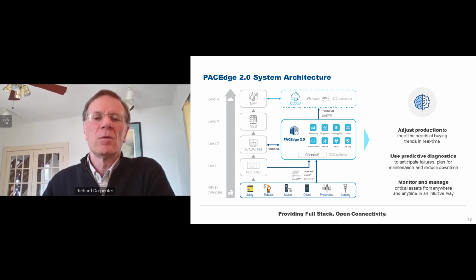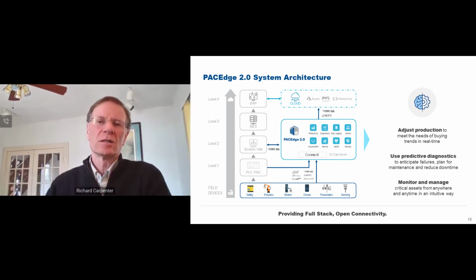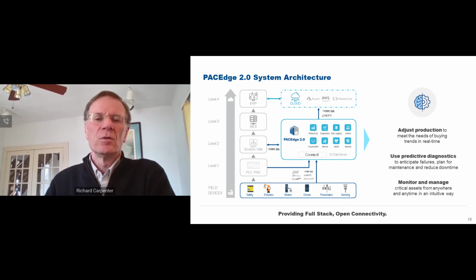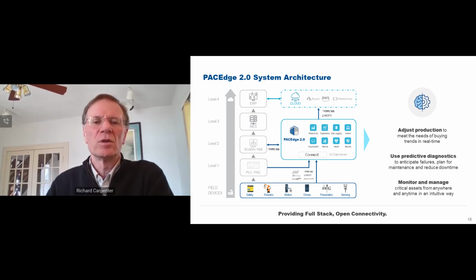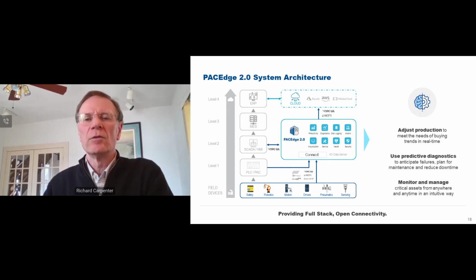And because this is on a plant network and it's fixed on that network, you really don't want to open it up. Whereas the new generation of edge devices typically have dual but completely independent networks, one to get on the control or plant network, but a second completely independent one to support the cloud-based networks, with no way to cross across the two from a security standpoint. Or the edge may even be closer to the MES system, either to supply data or to feed data. And so from an architectural standpoint, you really want to think about the edge as something that scales from something close to the equipment down in the bottom left of the chart, all the way through the level 2, level 3 systems, and then feeding the more cloud environments.